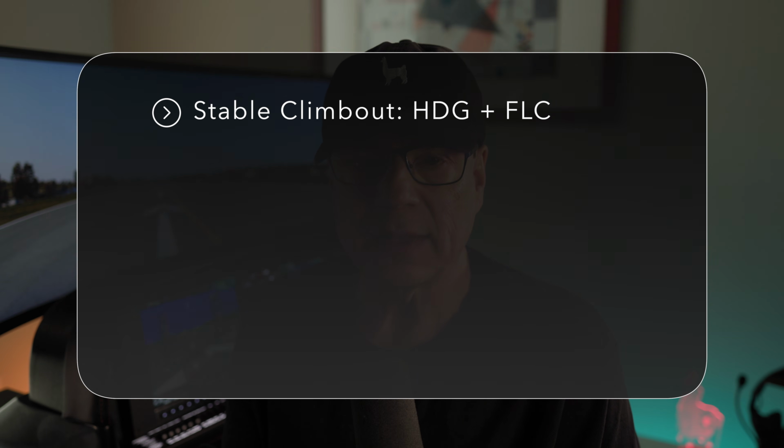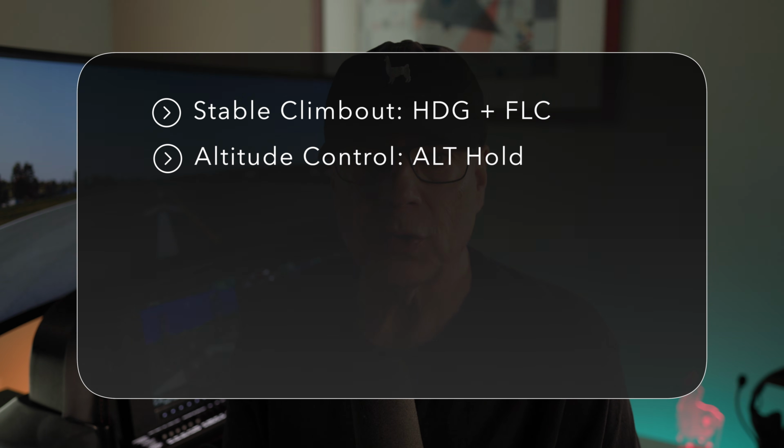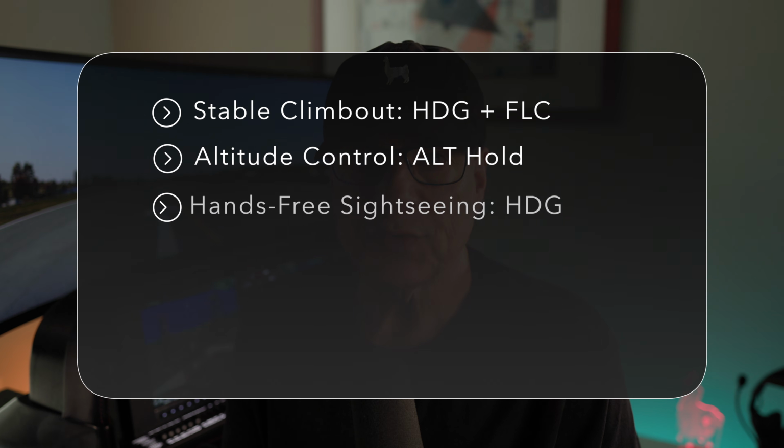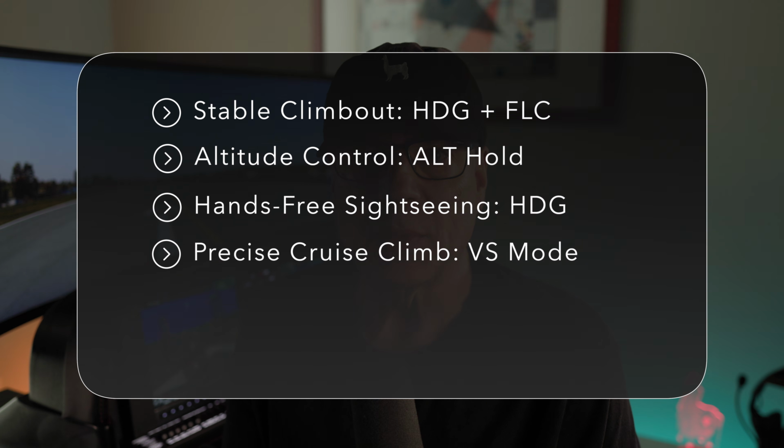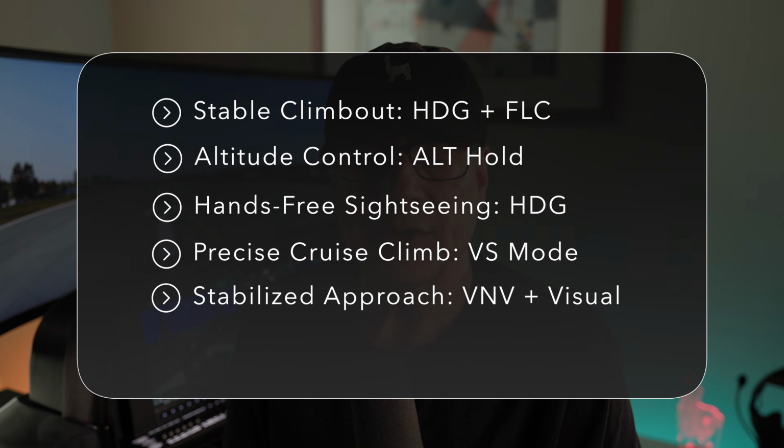Let's quickly summarize the 5 practical ways we use the G1000 Autopilot in this flight. Stable climb out with heading and flight level change, altitude control with altitude hold, hands-free sightseeing using heading changes, precise climbs with VS mode, and stabilized approaches using VNAV and the visual approach. These aren't edge cases. These are practical everyday techniques you can use on almost any VFR flight. And they aren't cheating in the sim. These are real-world techniques that transfer to actual flight training.